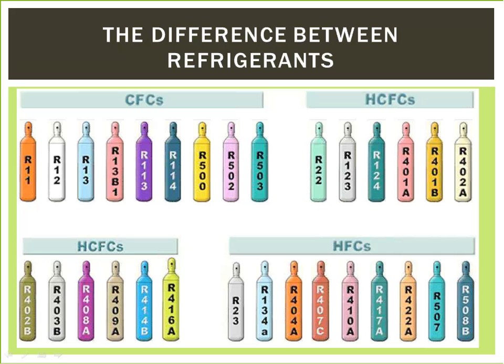Neither refrigerant can be used to top off a system that contains the other, and units designed for one refrigerant cannot be charged with the other. Cross-charging can result in poor or no operation, equipment failure, or in some extreme cases, create a safety hazard. This also means that R410A can never be used as a retrofit refrigerant for R22 units.